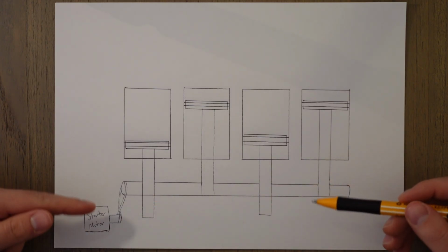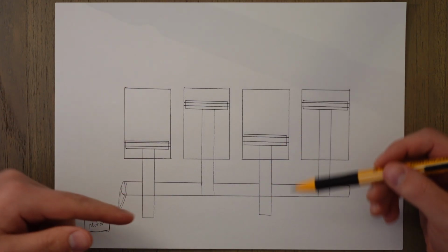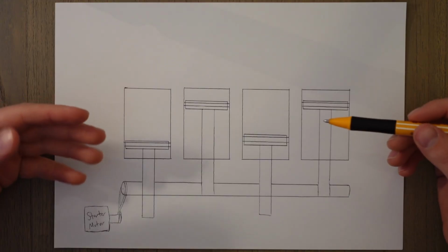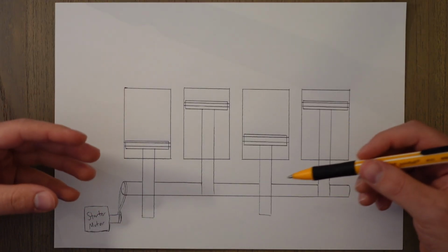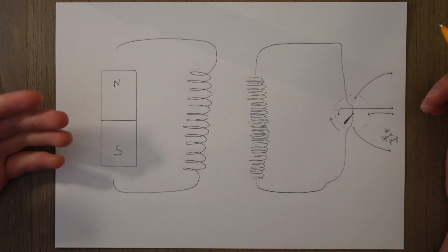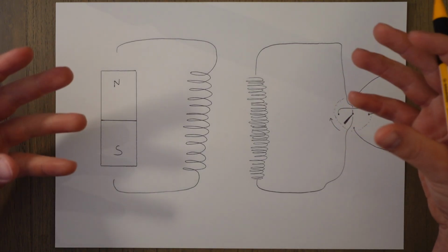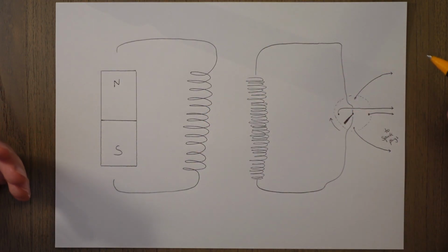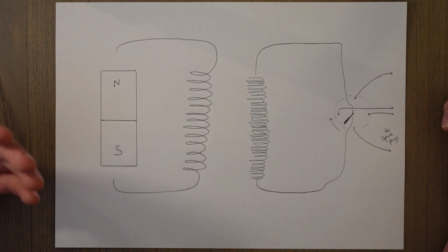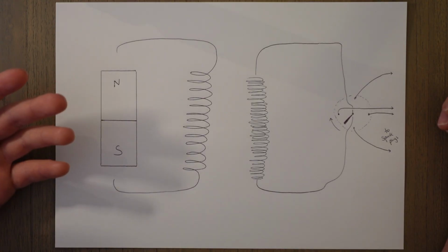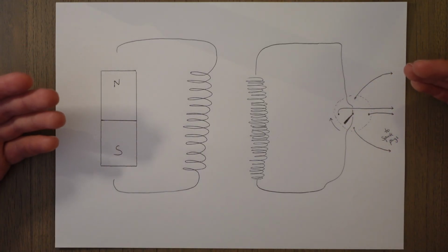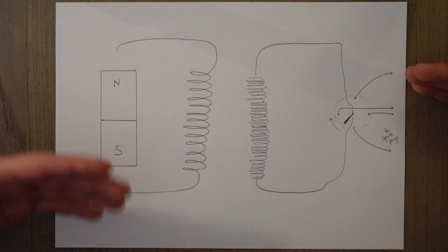It rotates the crankshaft in order to get the pistons moving in the correct motion and starting that suck, squeeze, bang, blow cycle. And once the engine is in the cycle and up to a sufficient speed, the starter motor disengages as it is no longer needed. An ignition system is used to create the electricity for the spark plugs in order to generate those sparks used in the combustion phase of the cycle. Sometimes the ignition system can be the battery, but more commonly used is a magneto system, as this is completely independent of the aircraft electrical system and serves only to generate the electricity for the spark plugs. And normally there's 2 magneto systems in case one of them fails.